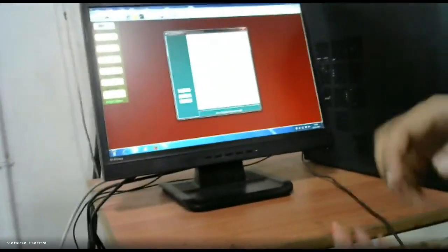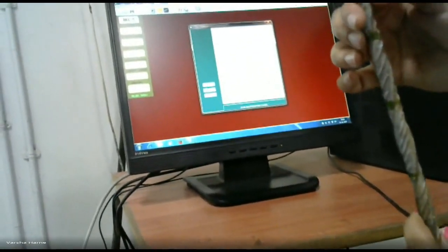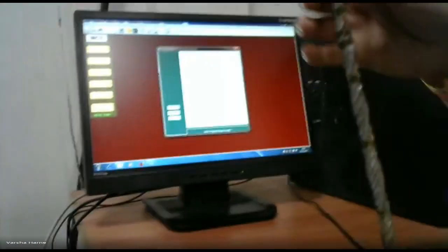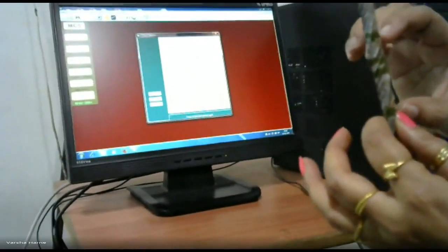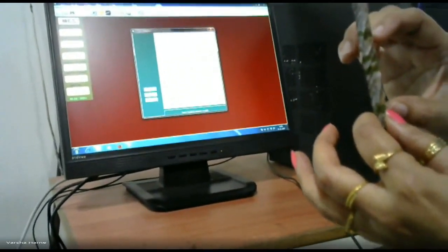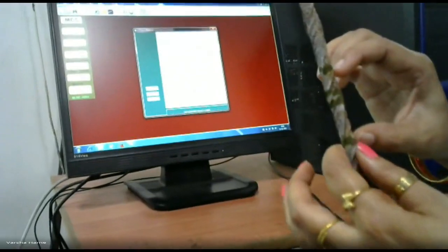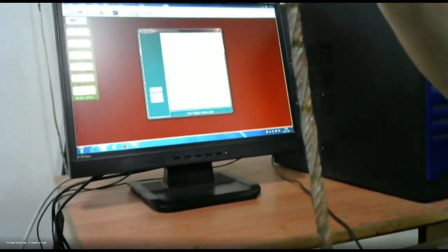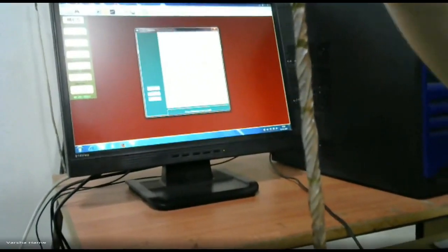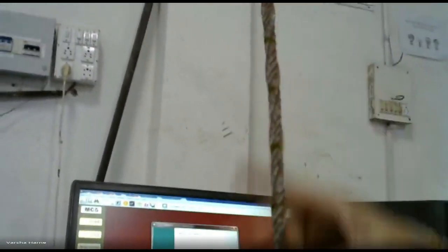How will it be obtained? Because we don't know where the bar will break. After performing that particular test, we have to join the bar again and check whether the length has increased or not. So it totally depends on our gauge length criteria. If we fix that bar, that's why we have to measure the bar. For example, if it is 600 mm, you have to measure the center.